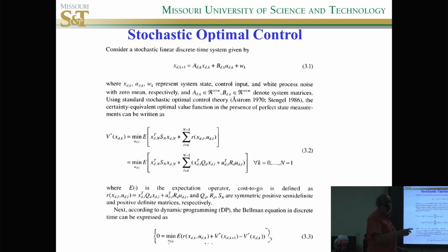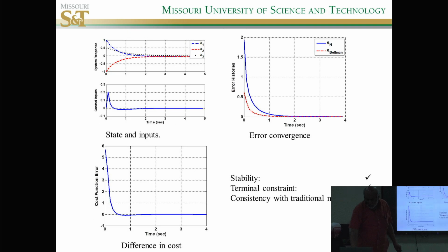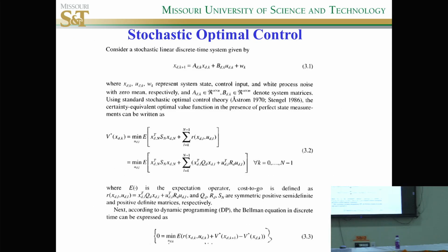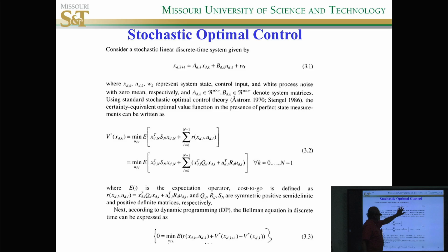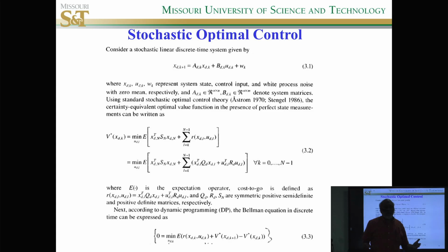Now we apply the same thing to the network control system. The only difference in this example is that the loop, which you have seen, becomes A_dk, and then you have B_dk. These are stochastic and time varying. But the process is identical to what you did. We use the same Q learning, except that A_dk and B_dk have random variables inside, but it works.